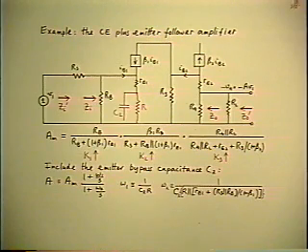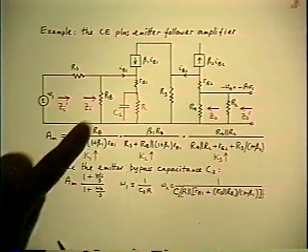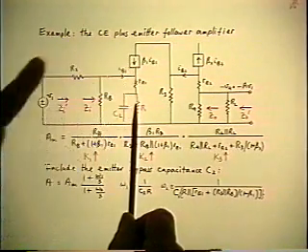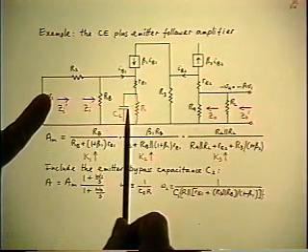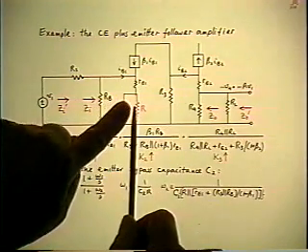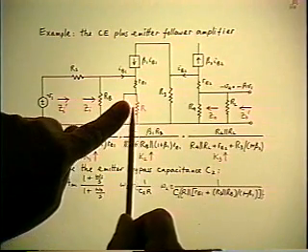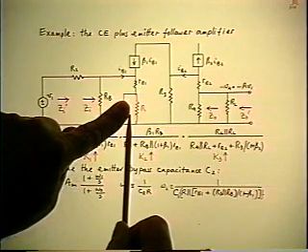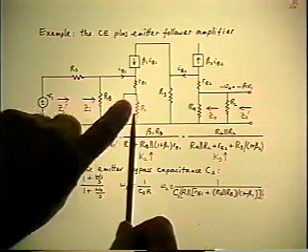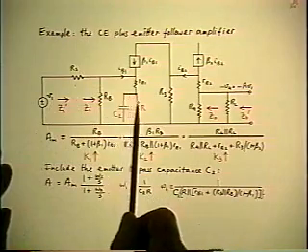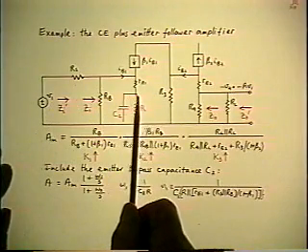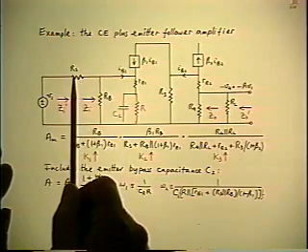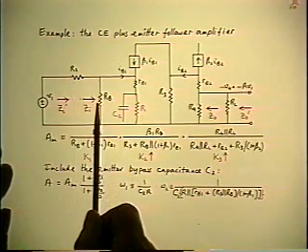So the RD is found by replacing the capacitor by an independent source, making the original input zero, and finding by single injection what the driving point resistance is, seen in place of the capacitor. By inspection in this case, if you look in from the capacitor, you're going to see R parallel RE1 plus the reflected RS parallel RB.